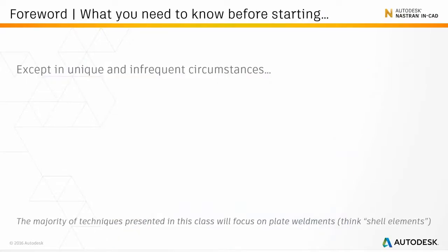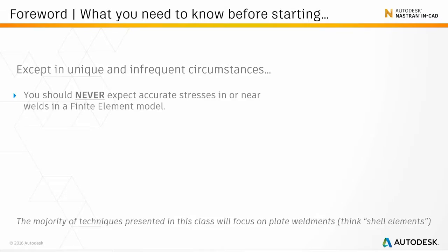So let's get into the content of today's webinar. Firstly, what do we need to know before we get started? Well, I need to stress that it's very unlikely that you will find that FEA stresses on welds will match that which are measured on an actual weld. What do we mean by this? If you were to run an analysis, come up with some results to show you stresses on your welds, if you were to then go and measure them, it's unlikely that you will find correlation or the exact number that you're looking for. So stresses are definitely an approximation inside of your FEA packages when you're looking at the welds themselves.